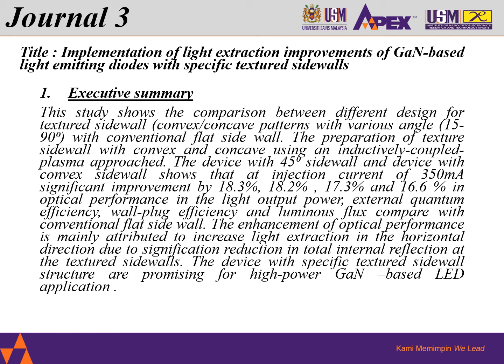This study shows the comparison between different designs of the textured sidewall, a convex pattern and a concave pattern, and mirror angle from 15 to 90 degree, with a conventional flat sidewall. The preparation of the sidewall with convex and concave patterns uses the inductively coupled plasma approach.